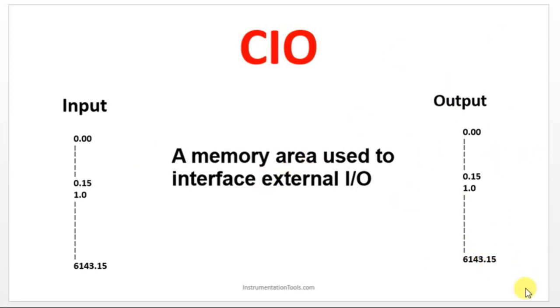Right. So let's see about output. For output addressing, we will be using the 100 series, 100.0, 100.7, 101.0 like that. In the integrated type PLC, you can use 0.00 and 100.00 for IO, input and output. If it is an expansion module input, you can make use of 2.0 to 9.0. So it is like 2.0, 2.1, 2.2 like that you can name it for the expansion module IOs.